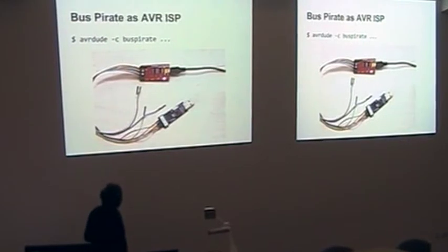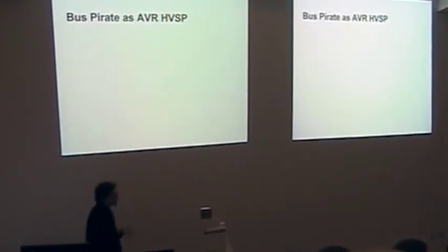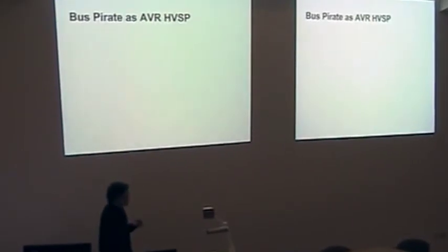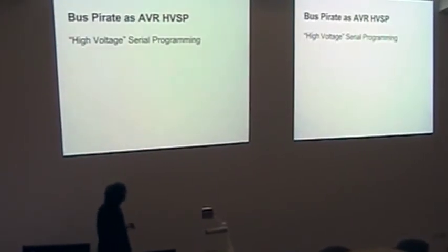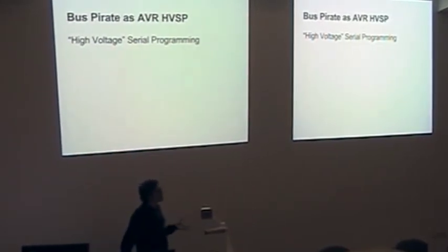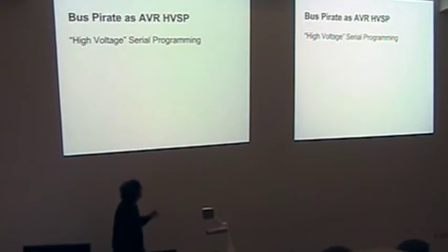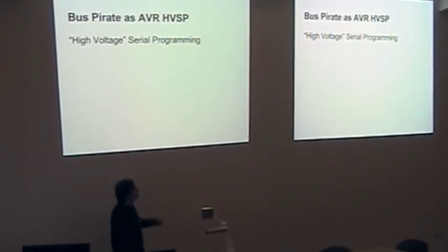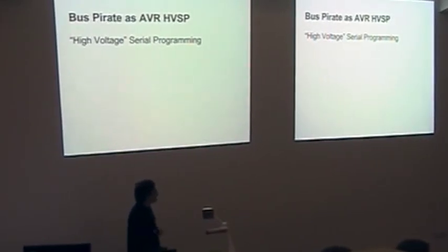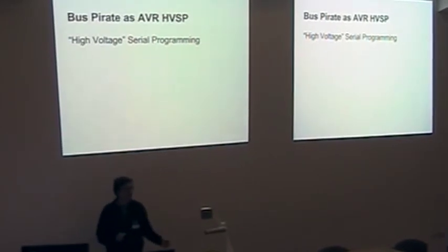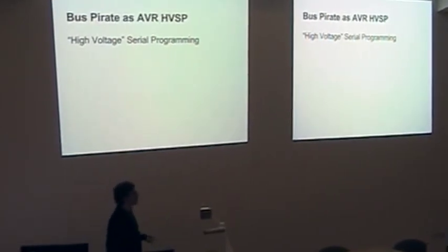Whereas everything else I'm about to talk about, I think so. So one of the first things I had to play around with: the AVR chips, usually you program them through SPI, and when you're programming these over SPI, you need to knock it into stop what you're doing and accept this program mode. So it has a reset pin, and you pull the reset pin low, and that acts like the chip select line. Talk to it.